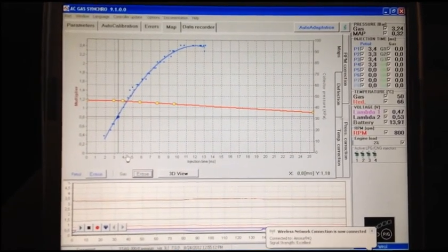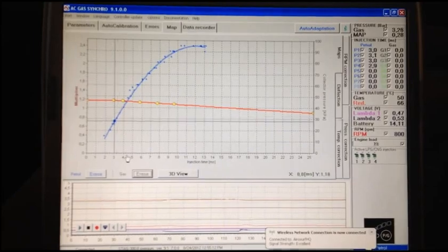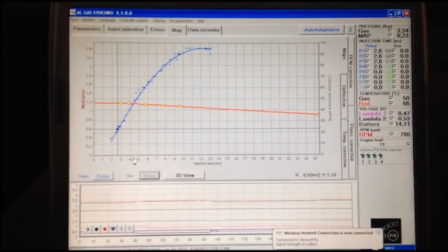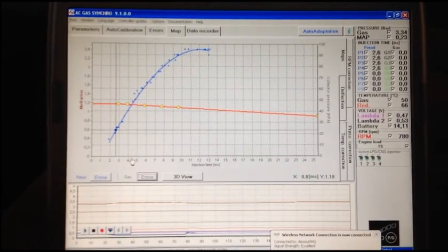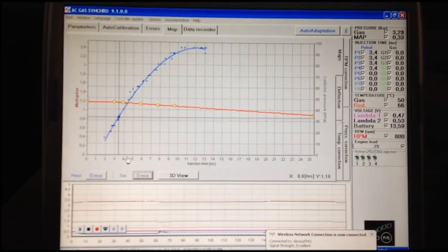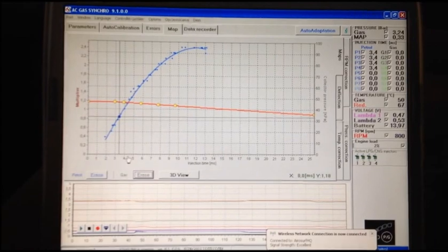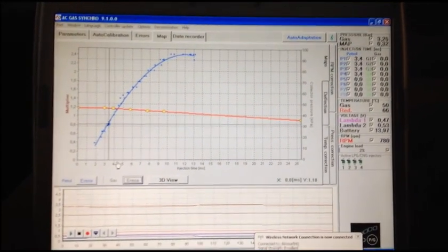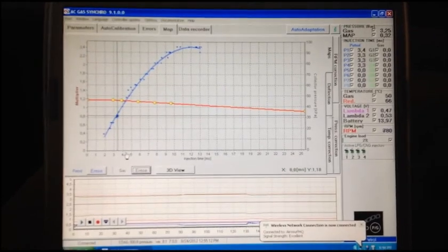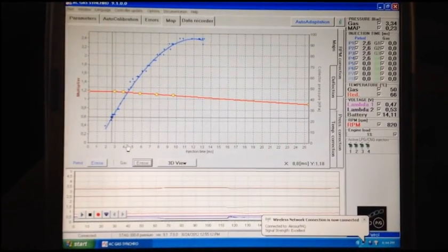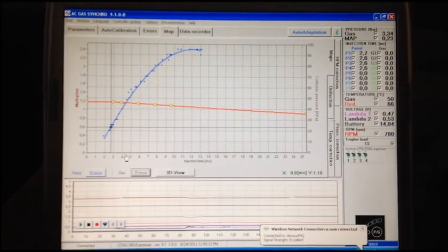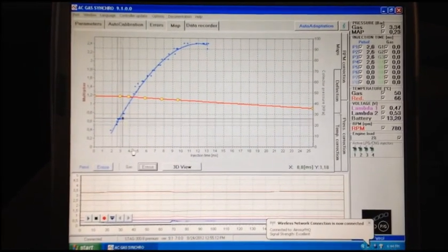For the most part, you can get it extremely accurate this way. It may be easier for some people, and it may be a little bit more predictable if there's extreme shifts in outside temperature or something like that. It may hold it a little bit more accurately, but generally, if you get this part dialed in perfect, there's not too much of a need for that OBD interface. But it does make it nice because you can see the fuel trims and your error codes right on the laptop in the same software that you're seeing here.